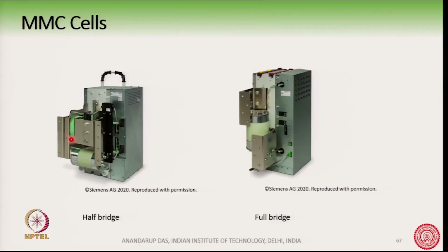In here, this green colored thing is probably the thyristor. The anti-parallel or two thyristors back to back is the triac, which has this bypass feature which helps in the bypassing of the cell in case of a severe fault. Also you have the circuit breakers here inside these boxes. So, this is the arrangement whatever you can see in the picture.